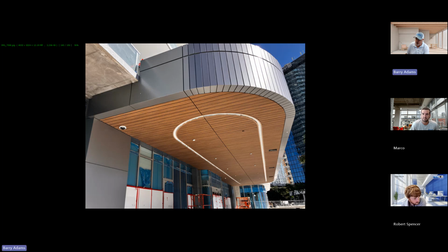And our installers originally went out there and misaligned the light track. They put it where they thought it should go, as opposed to where it was designed to go. And we already had all this ACM cut. So it's like we either recut all the ACM or you put it right where it was designed to go. And I gave them all the information they needed.